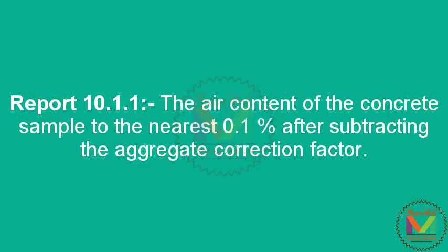Okay, we have got the report, almost the final section. As per section 10.11, we report the air content test result. It shall be reported to the nearest 0.1% after subtracting the aggregate correction factor.